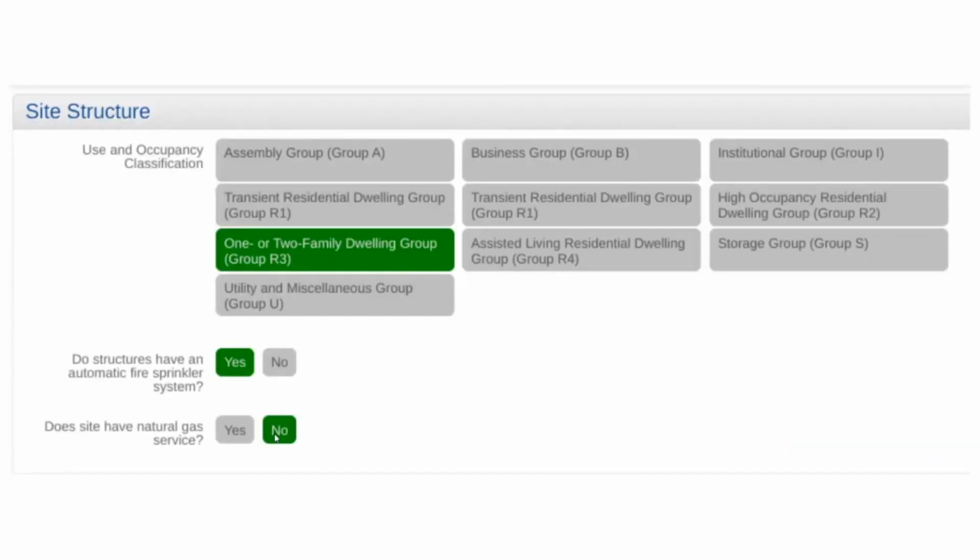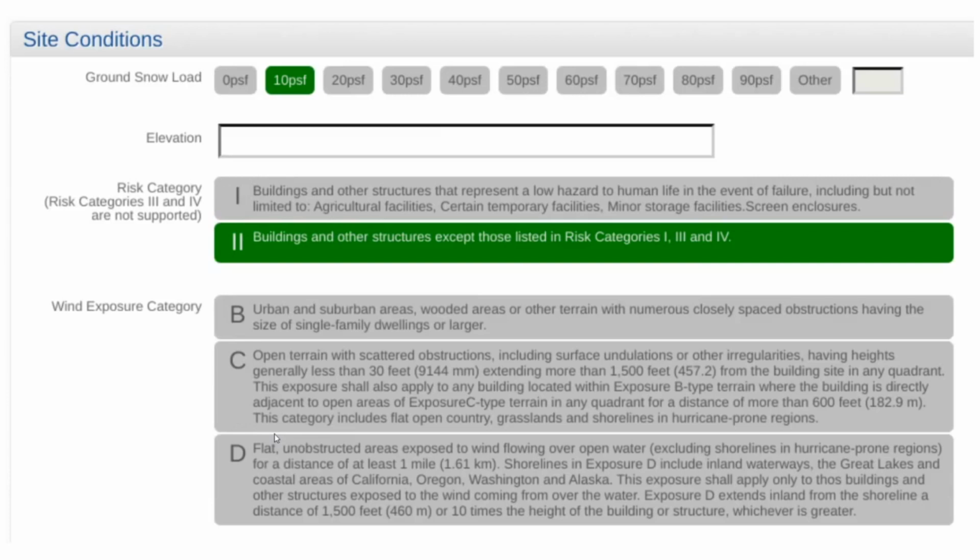Site conditions inputted include local building code and wind speed, surrounding terrain, which will then be called out in the final permit documents. This information is used when using manufacturer provided sizing tools, such as racking sizing software or even inverter circuit sizing software. So at this point in the project design process, this information should already be known.